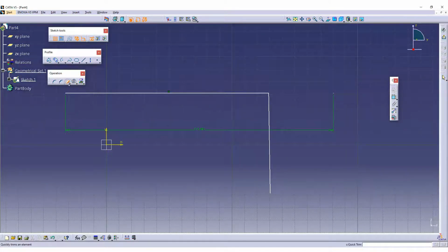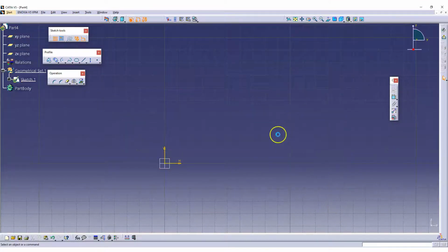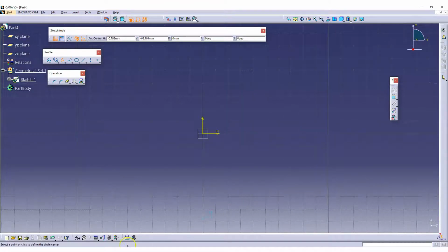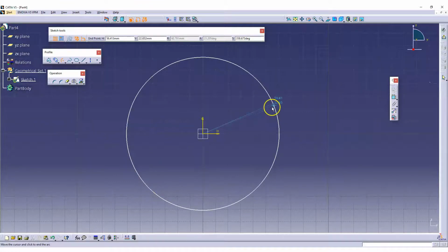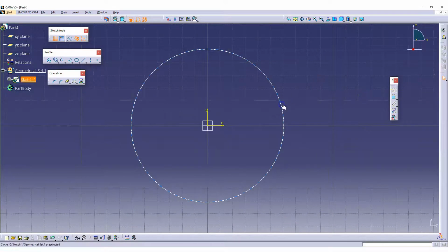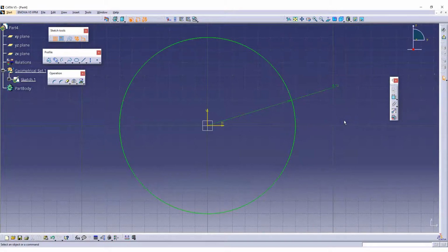And then we are going to understand some of the features. Say for example, closed loop. See this one. I'm just going to close it, and I'm going to use a profile here. Putting a normal view. Put normal view. Intentionally I'm going to draw the circle, and make the circle. And I'm going to give this dimension. And you feel that this sketch is fully constrained, right? 70 mm. The sketch is fully constrained.